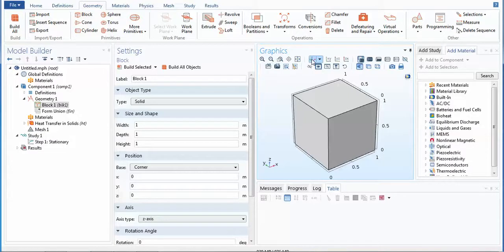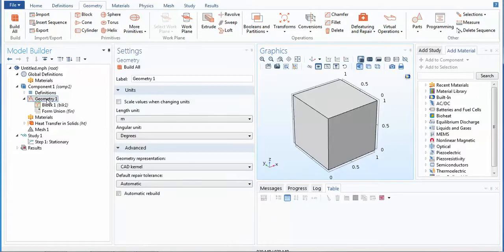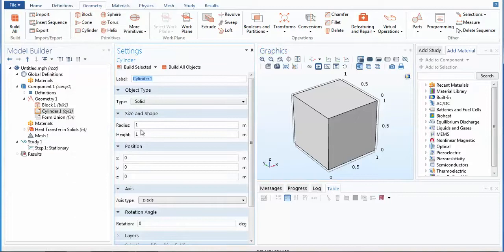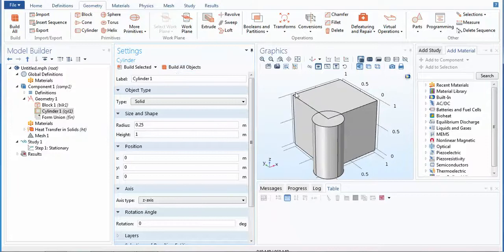If I wish to construct a hole in between the cube, the option will be the same. You have to use basic Boolean algebra, like in two-dimensional geometric construction. So this is one thing. I wish to make a cylindrical hole, so I choose a cylinder and a radius a little bit small, and construct it. You can see the cylinder constructed with this radius, but position is important. So if you wish to check the position, you go face-wise.